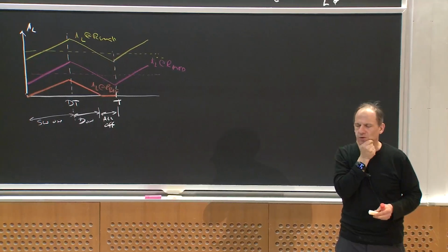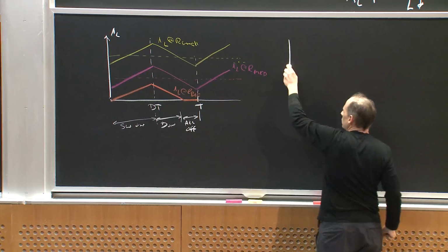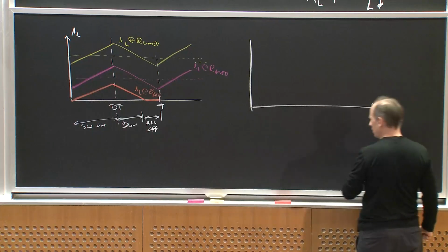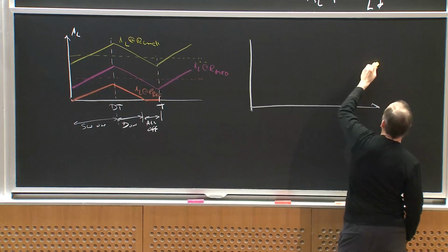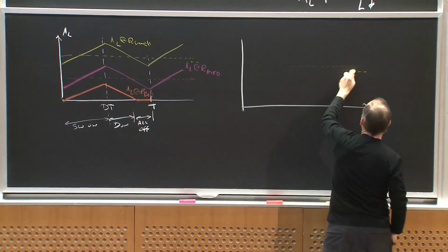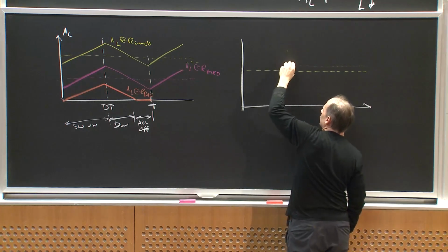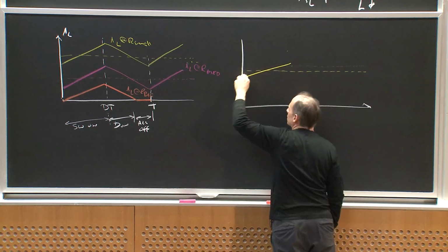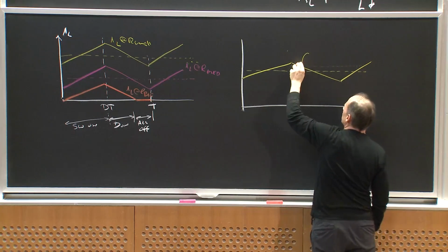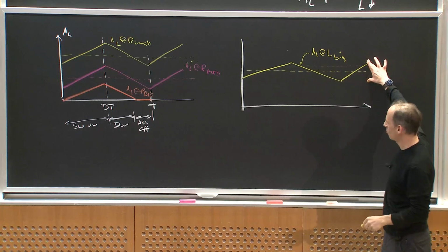Okay? What happens with variations in inductance? Well, slightly different. Maybe what I have is this. I will have, again, some value IL. Maybe make it a little smaller. I have some average value of IL that I'm generating, and if I have some big inductance, maybe my ripple is small, so it does this. So this is IL at L big. I have a big inductance in there, the ripple's relatively small.